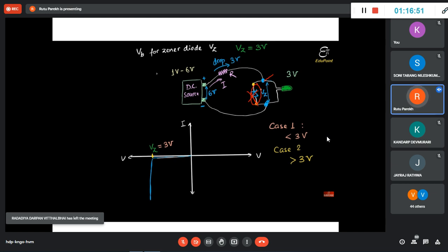But my point to you was, I was explaining from the Zener point of view, okay, what is going on inside the Zener. So less than 3 volt, it was not conducting. Greater than 3 volt, it will start conducting. And what will change is the voltage will remain almost constant. What is changing is the I through the Zener.